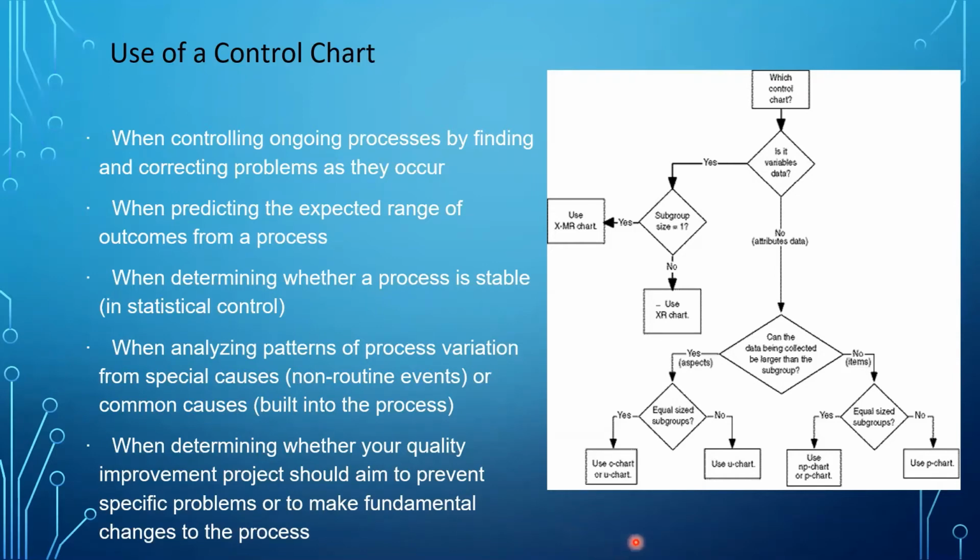Correct control chart selection is a critical part of using control charts. If a wrong control chart is selected, the control limits will not be correct for the data. The types of control chart required are determined by the types of data to be plotted and the format in which it is collected. Data collected is either in variables or attribute format, and the amount of data contained in each sample collected is specified. This algorithm is used to select what type of control chart should be used.